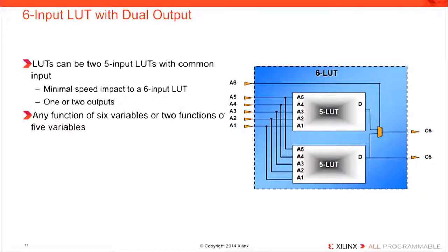The key thing is the tools will put those 2 functions in one lookup table provided both functions are of the same Boolean variables. If they are different even in one, then it will put them into 2 different lookup tables.